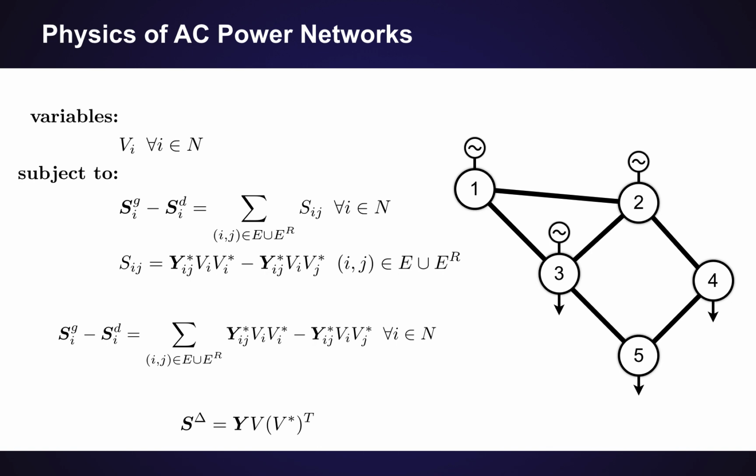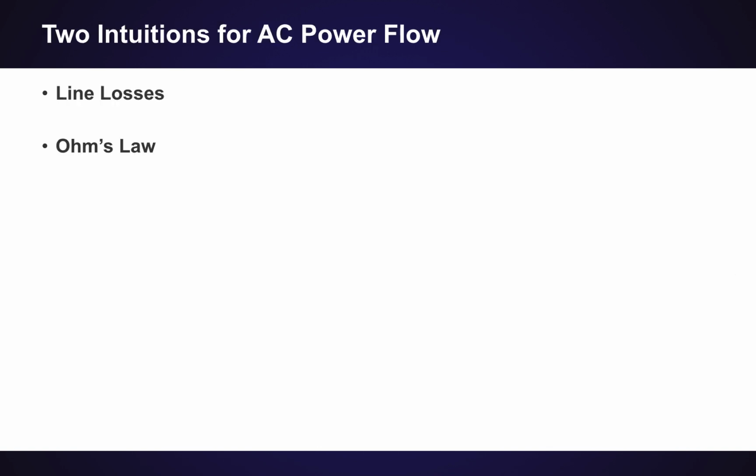It's worthwhile to note that this is a very stylized version of an AC power network. So in practice, you would need to define things like a slack bus, PV buses, PQ buses, and kind of set up a power flow study. We're not going to go into the details of how you do that here because we're going to jump directly to AC optimal power flow where that isn't necessary. So we're just right now going to skip ahead, and if you're interested, read a power system textbook on how you can formulate a proper power flow problem.